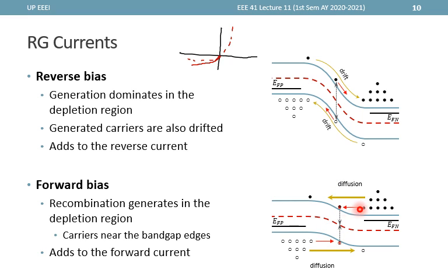There are more electrons at this lower portion and there are more holes at this lower portion, so the most likely to recombine are these electrons here and these holes here. Now these electrons here, in our ideal analysis, are not able to produce current, but this time since they recombine, some forward current is actually added. So instead of following our dashed line right here, we'll have more current than expected. Okay?